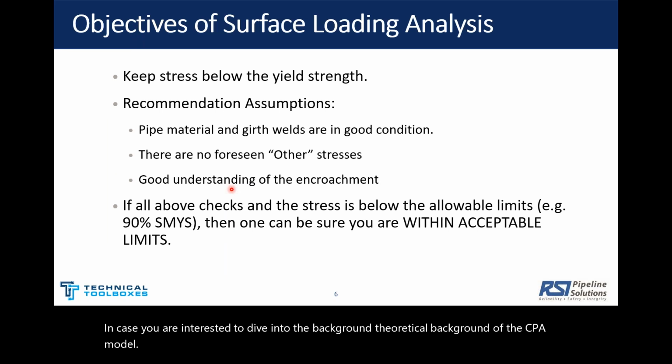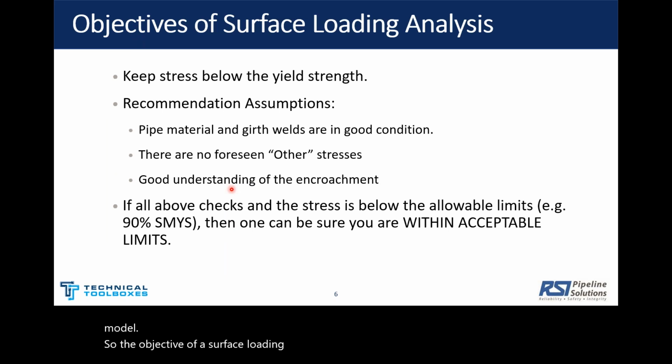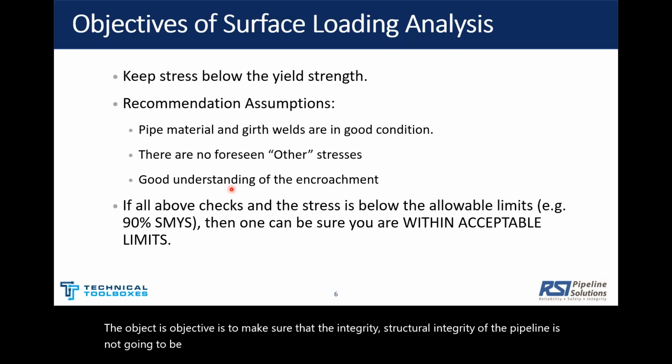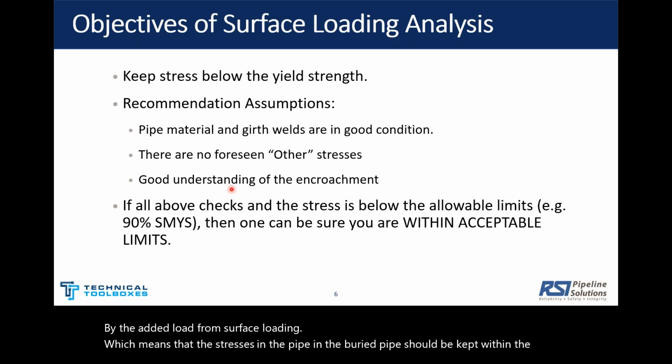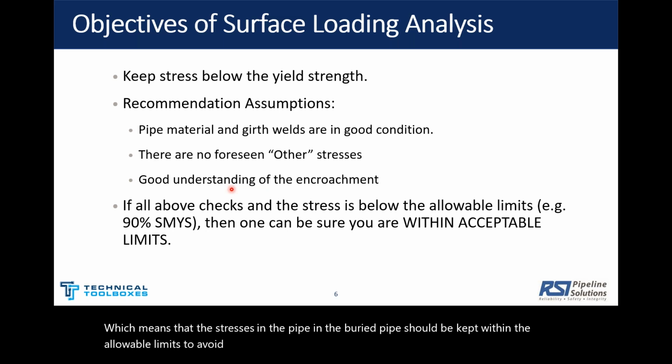The objective of a surface loading stress analysis is to make sure that the structural integrity of the pipeline is not going to be affected by the added load from surface loading, which means that the stresses in the buried pipe should be kept within the allowable limits to avoid yielding of the pipe.